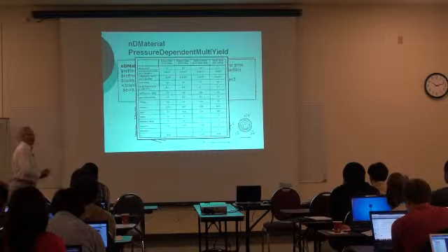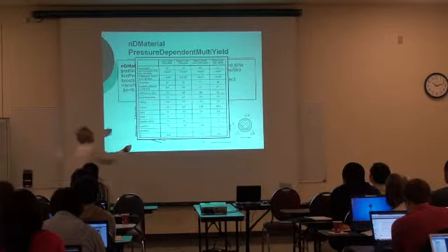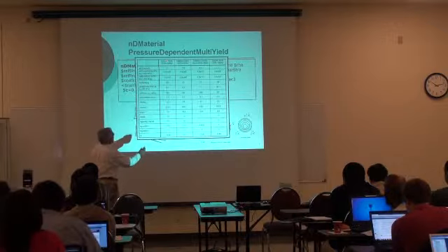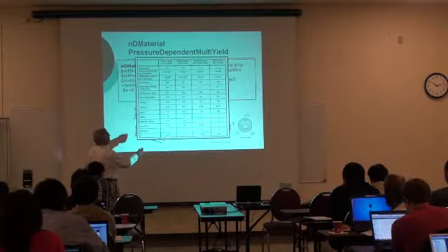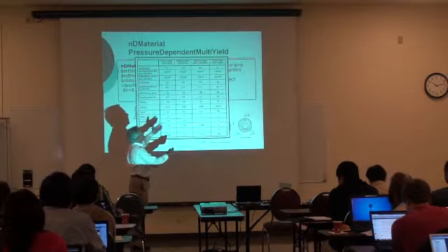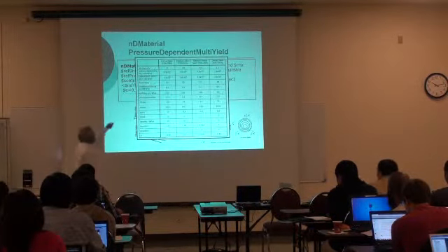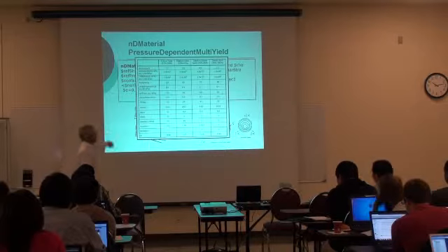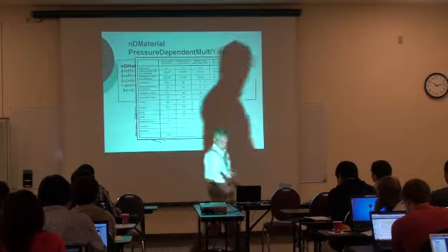And that's what Kamal did. So he said, look, for a loose sand, that means relative densities in between 15 to 35, or medium sand, medium dense, or dense, these are typical parameters that you can use for that particular model.